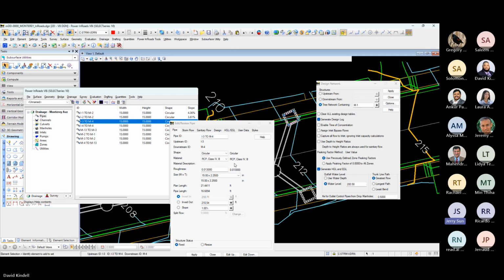The box, the inside and the outside, they have like a 9-inch or 6-inch thickness. So you need to put the box along the front of the curb. That's the way you can get the right pipe length. Otherwise, the pipe length is wrong, and your offset is wrong also.